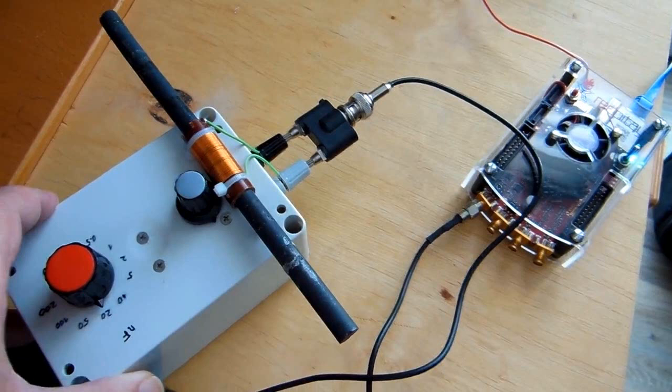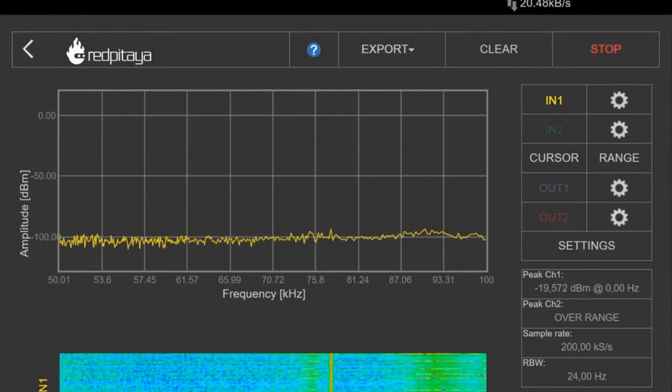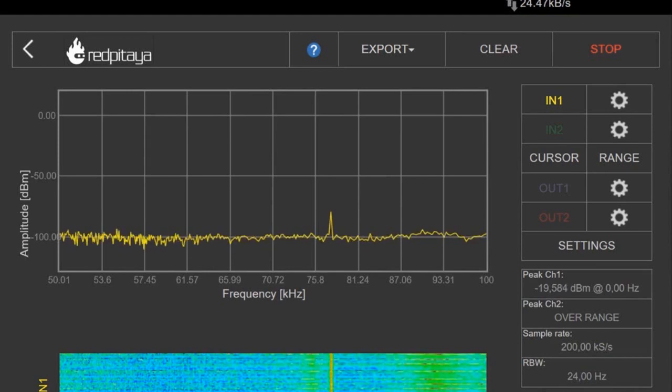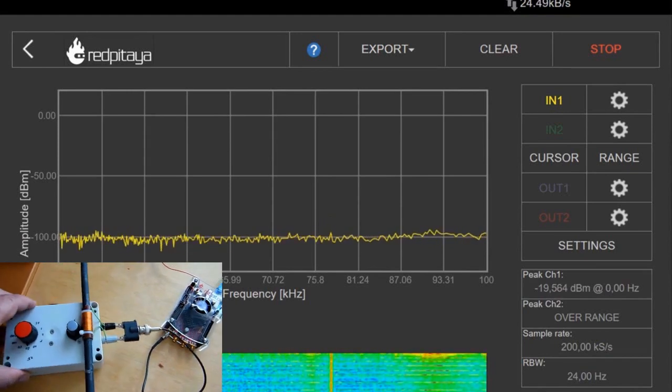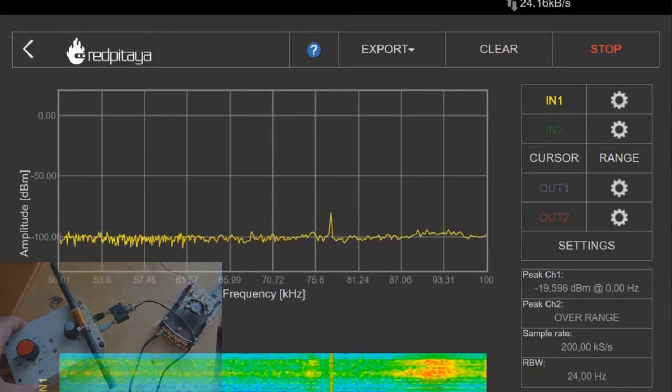in Western Europe. A tuned resonant circuit consisting of a coil on a ferrite rod and a parallel capacitor offers measurable signals, shown by the Red Pitaya, a small modern oscilloscope with web-based applications. As you can see, there is an obvious peak at a frequency of 77.5 kHz, and it depends on the ideal direction. In a time of 1 second the magnitude varies, and the duty cycle of each low and high magnitude defines a high or a low of a bit.